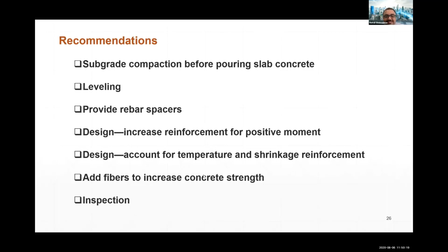Lastly, inspection during construction and checking the tolerances are necessary to ensure the quality of the work, and they can guarantee durability and reduce repairs. Transverse joints must be appropriately placed and constructed and filled with flexible materials to avoid crack development.